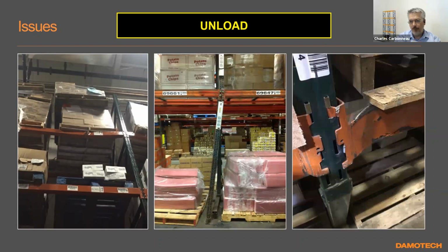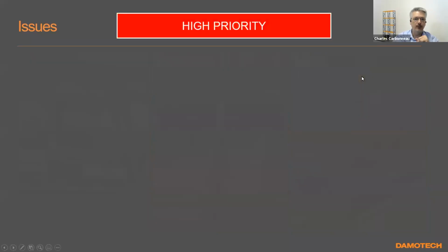And a badly damaged beam, but with repeated impacts. You can see this has got to be, I think it's a reach forklift. And you can see the bottom tooth that's been torn and the top one about to go, and there's still pallets there. So therefore unload.